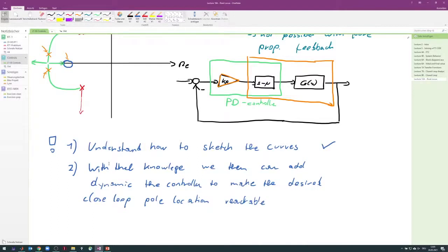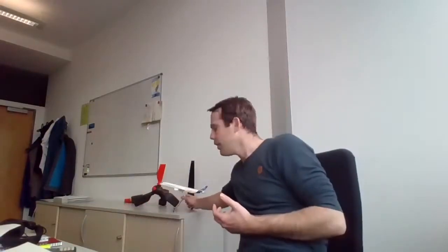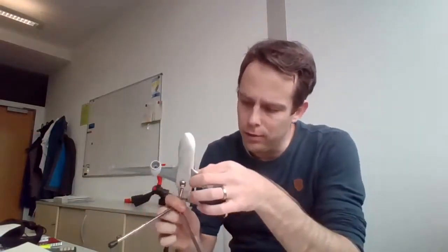controllers using the locus curves. And I hope that you kind of understand at this point that we are not really restricted to PID controllers, right? Because you can add here what you like, zeros, poles, and so on, right? But usually a PID controller with its two zeros and the integrator is a good starting point. They mostly work, but not always, especially when you have flight control problems where you, for example, consider a structure which can vibrate. Oh, it's going to break.